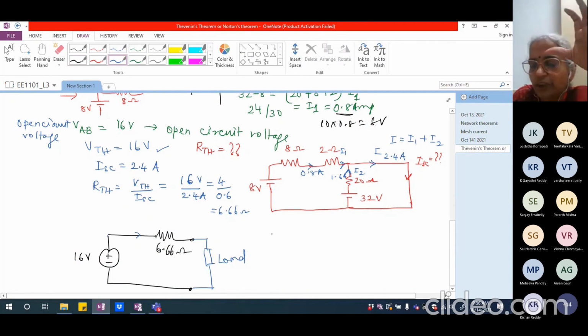So if I know exactly what the input side circuit is, which can be represented by a Thevenin's equivalent with a particular voltage source and a particular impedance, then I can say how the power distribution system behaves for different variable load conditions of my residential or commercial complex. I will be able to predict this quite easily. Okay, so that is where the Thevenin's equivalent circuit comes in really handy.